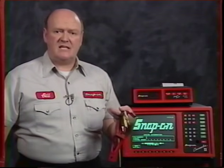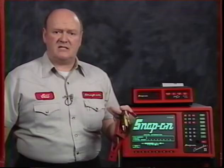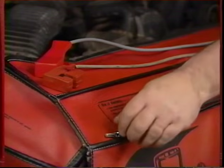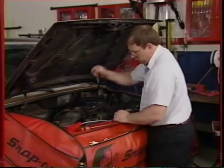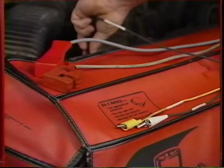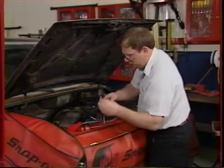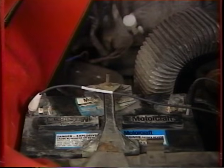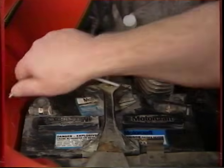The Counselor 2 uses a simple 6-lead harness to obtain the electrical signals from the engine that are needed for the various test screens. The lead set plugs in here. The black lead is the ground. It will attach to the battery's negative terminal. The white lead picks up battery, alternator, or voltage signals. Attach it to the battery's positive terminal or move it to the voltage test point.